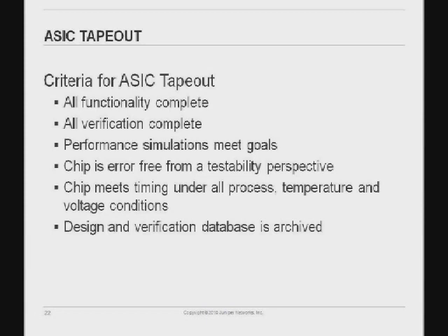We are there. And the chip is also error-free from a testability perspective, because these chips are very complex devices, and in manufacturing there are defects, and we need to weed out those that are defective. So we have design-for-testability logic in there to test the chips too. And the chips also meet timing across all the process, temperature and voltage conditions. All these silicon devices depend on the temperature and everything; they actually have different timing. We have to make sure they work at all conditions. And then we archive all the databases, and then we tape it out.